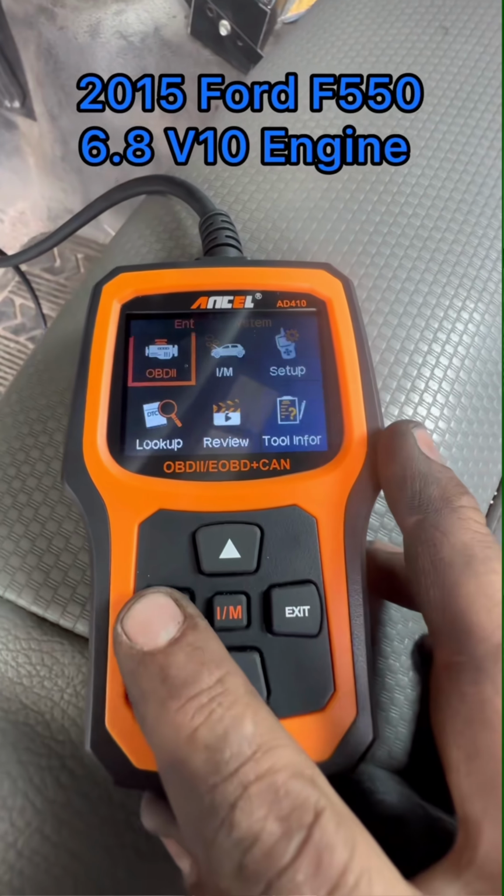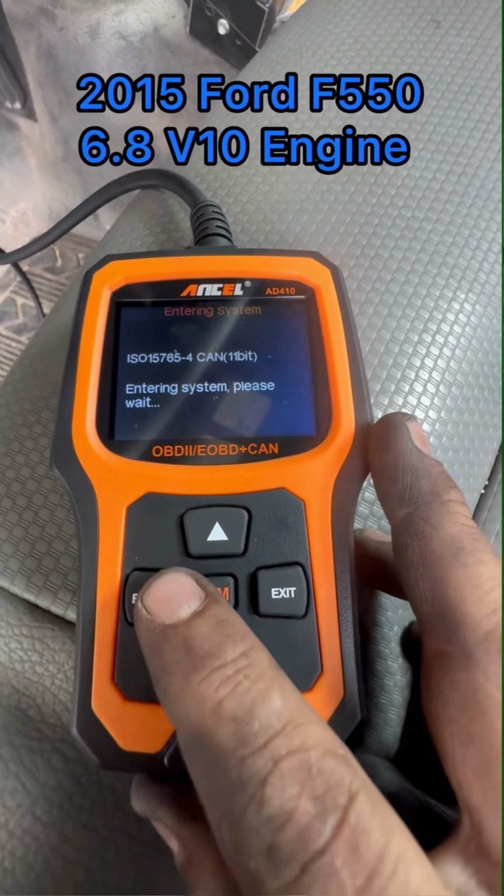Got my little Ansel AD410 scan tool hooked up and ready to go. There we can see we don't have any fault codes in the engine ECM. Let's take a look at some of the engine data. There you can see with the ambient air temperature at 69 degrees, the intake air temperature was at 125 degrees with the key on, engine off. From what I've seen in the past, the intake air temperature shouldn't be reading that far off from the ambient air temperature. So we know that's a problem, but is that our problem?